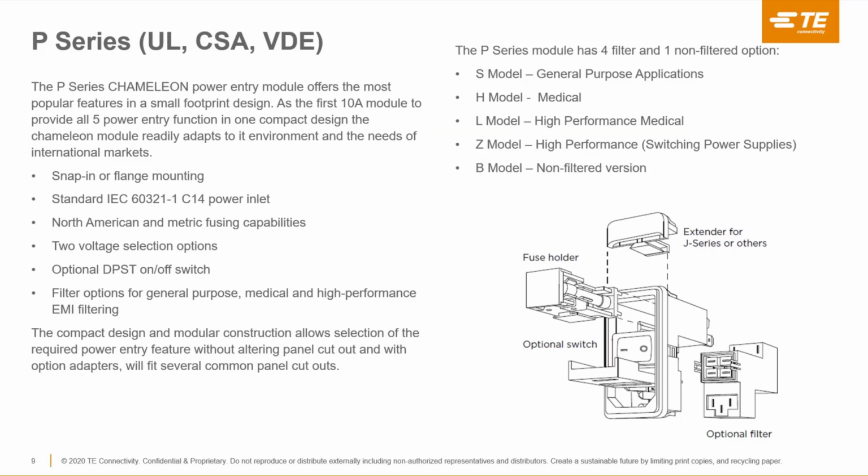So again, it's got a snap-in or flange mounting. It uses an industry standard C14 power inlet, North America and metric fusing capabilities. You have a 2 voltage option or selection option, and then optional on-off switch. Filter options for general purpose, medical, and high performance EMI filtering. So if you have any customer needs for a power entry module, you can probably meet the needs with the